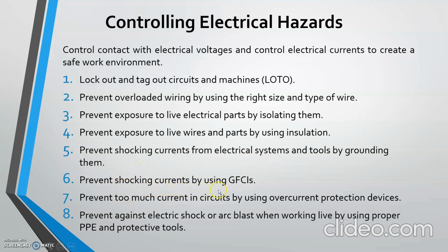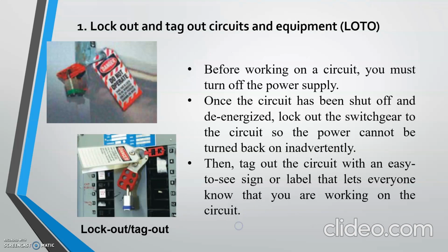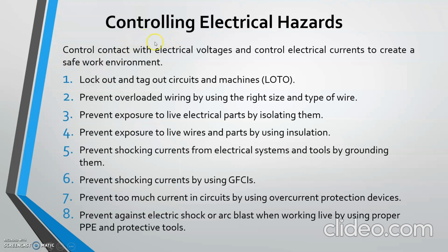Prevent shocking current by using GFCIs. Prevent too much current in a circuit by using an overcurrent protection device. And last but not least, prevent electrical shock or arc blast when working live by using proper PPE and protective tools. So I'm going to discuss controlling electrical hazards, number 1 and number 6.